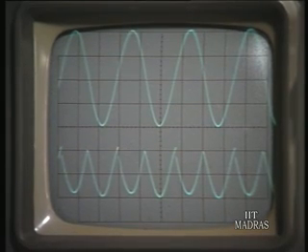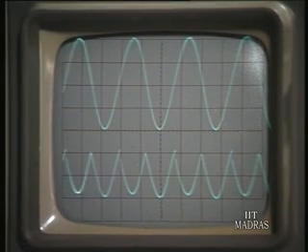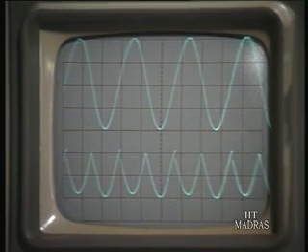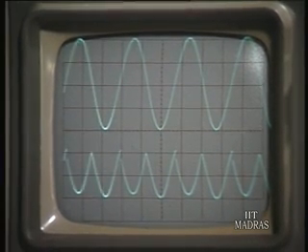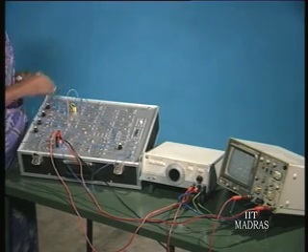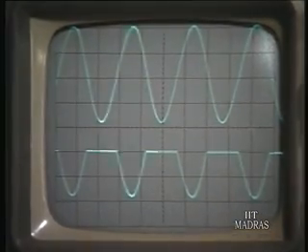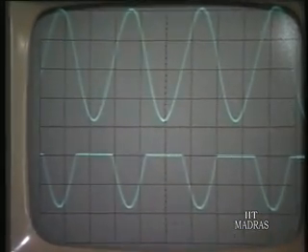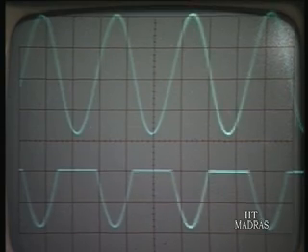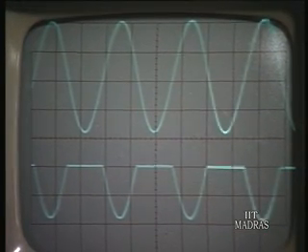You can see that the waveform is there, but it is showing full wave output instead of the expected half wave. Now, she will connect the other diode, and you can see that the output is going to be clamped to 0 when the other diode is not conducting. So, you can see that this is a half wave rectified waveform.